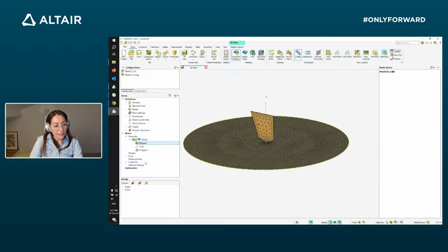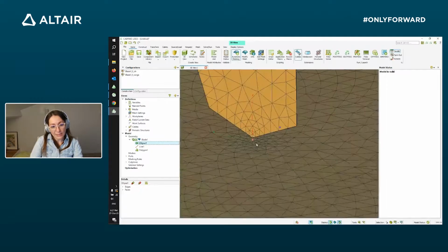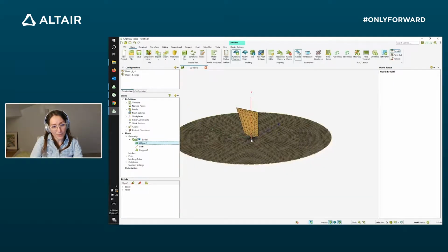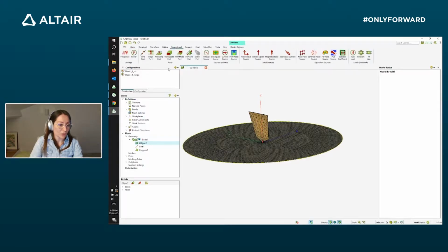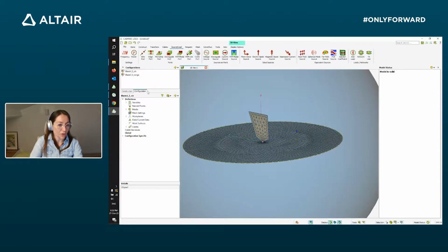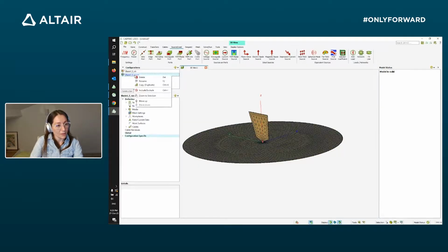So let's see. Our antenna has already a predefined port here, and we will try to launch the simulation. But first, we will also define specific requests. So let's first check our configuration. Under the configuration tab, we can see what type of sources have been defined for our antenna. So in this case, it's a voltage source. And let's run our simulation.